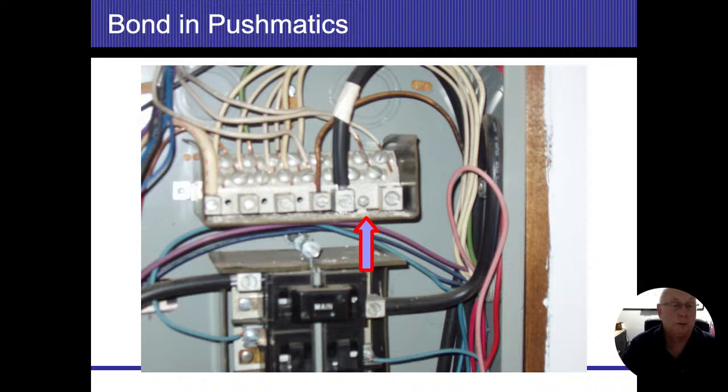There should be, I should say, a schematic on every panel that shows the neutral bus bars, the breaker bus bars, and on there you're going to be looking for a phrase that says bond when required, and it's going to be pointing to a certain hole or slot. That screw needs to be filled in there. Now, we're not going to know if they put the right screw in there. Somebody could have put the wrong screw and it doesn't go all the way through. We're not going to back these things out and verify it. But we should be able to verify that most likely it is there.